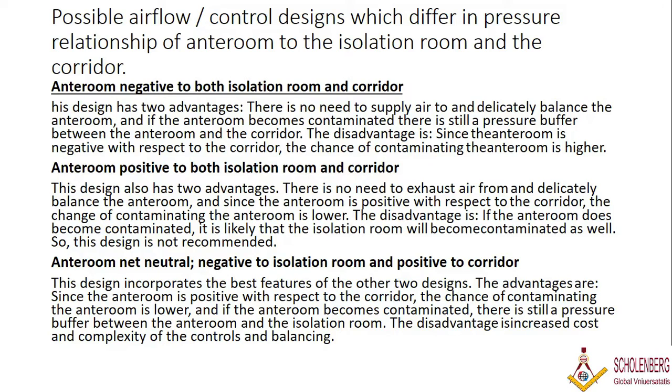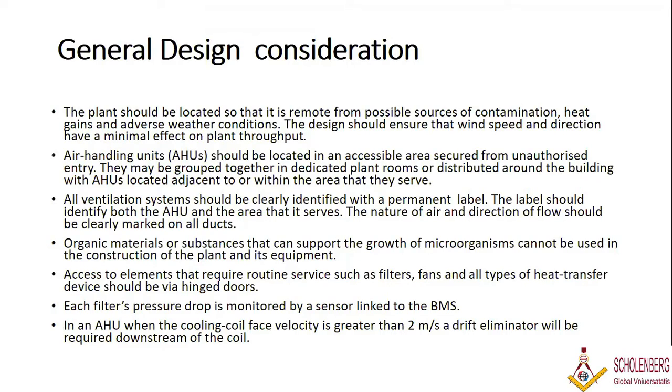The anteroom can also be net neutral, or negative to the isolation room, and positive to the corridor. There are various options, and you can check them out. We will see all this when we do the case studies and design. But in general, these are the general design considerations. This is just for general purposes, because in the first module I am just briefly explaining what we are going to talk about.